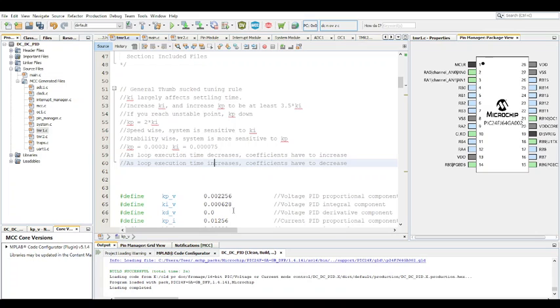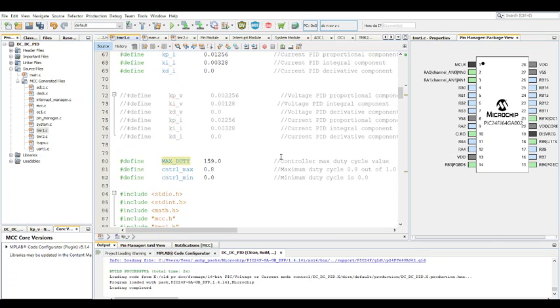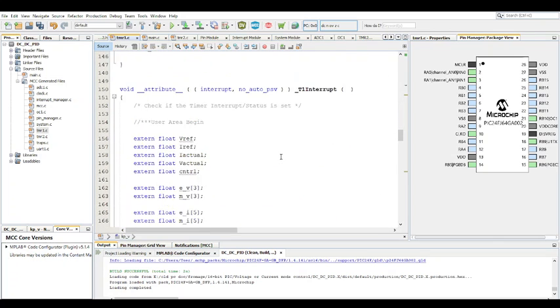But personally, I like to start really low and ramp my way up slowly. It takes a bit more time, but each system is different, and you just never know what a system is like. Even mathematically, you can calculate all day, and there might be a resistance somewhere that you're not accounting for, and it ruins your day. So I prefer to work with the system in front of me, see what it's doing and go from there.